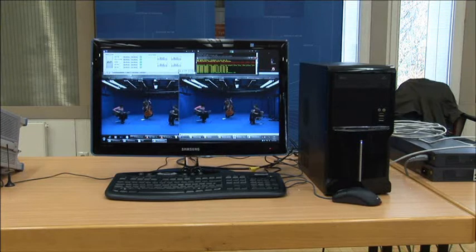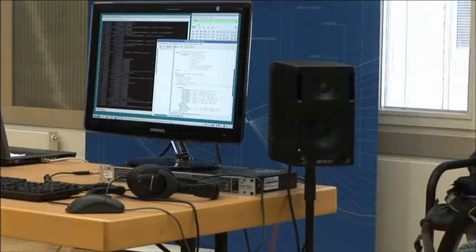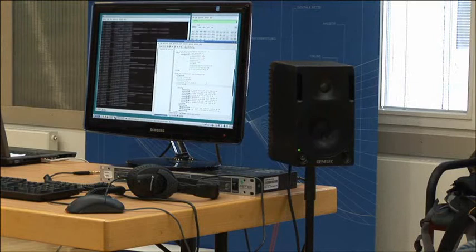We can now see the video rendering PC, which contains demuxing, decoding, video rendering modules and control modules. Two stereoscopic views are shown locally on the monitor, which are being streamed via DVB-T and IP. This is done to check that the video is being delivered correctly before connecting it to the stereoscopic display.